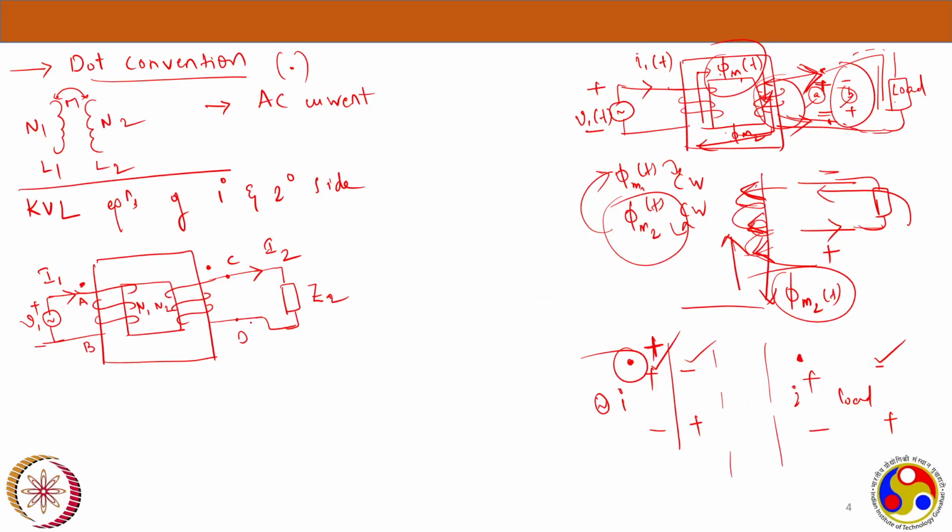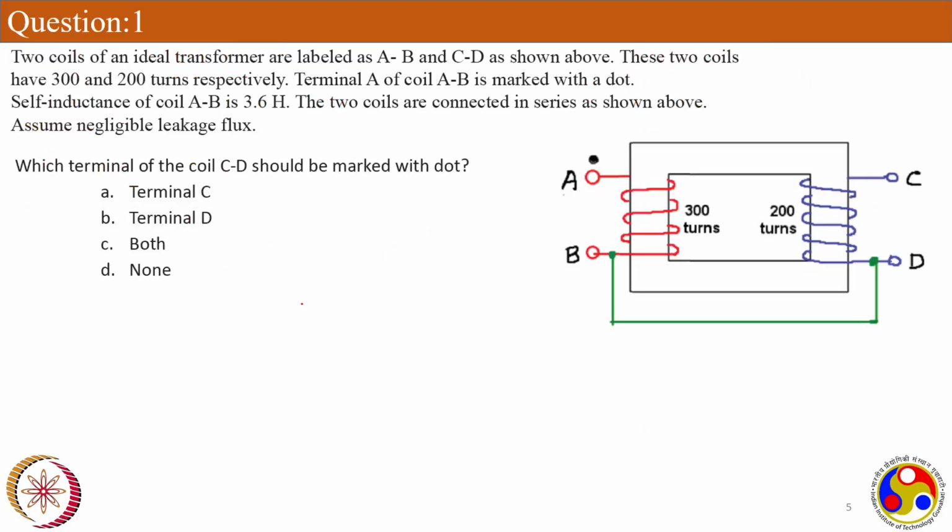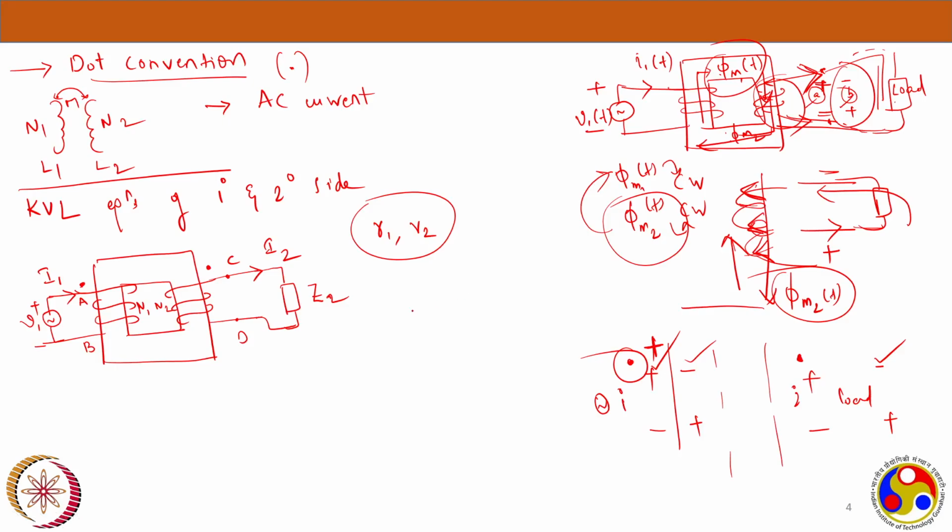Now let's assume these windings have some resistances with them. Any winding may not be a very pure conductor, it will have its own resistance. I am taking those resistances as R1 for the primary and R2 for the secondary. Now I can show the entire resistance of the wire as a small lumped R1 and the entire resistance of the secondary as a lumped R2.